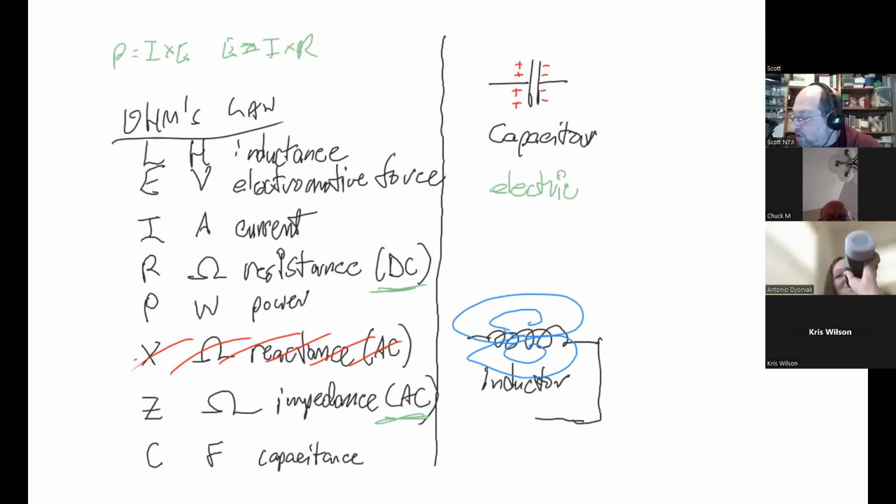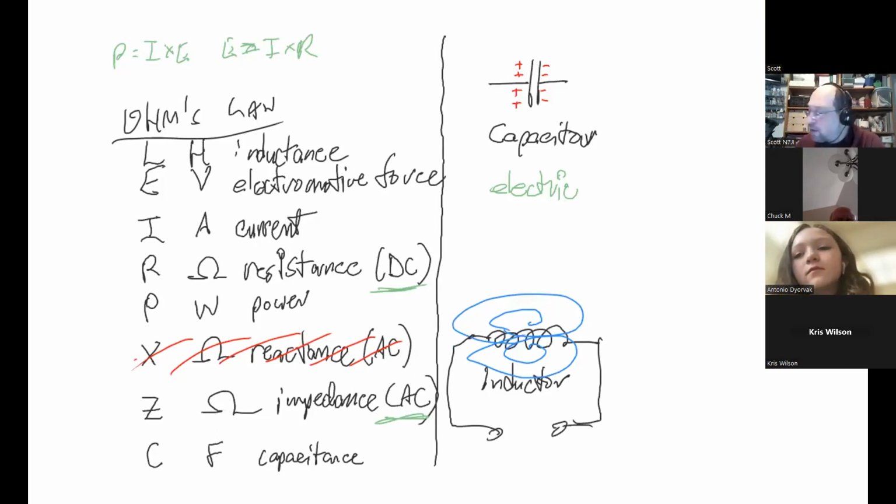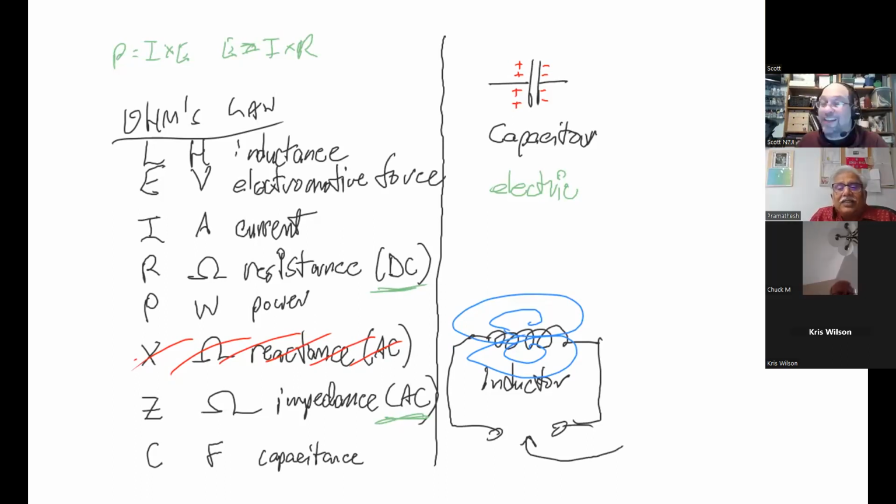What happens if this resistor actually looks like this? What's the resistance right here? Zero? Infinite? It's not zero, and it's not infinite either. Air is not an infinite resistor. Let's say this has a resistance of 10,000 ohms. What will happen is that you will generate a voltage that goes higher and higher until it generates enough voltage to say, okay, I just jumped the gap. Dielectric breakdown.